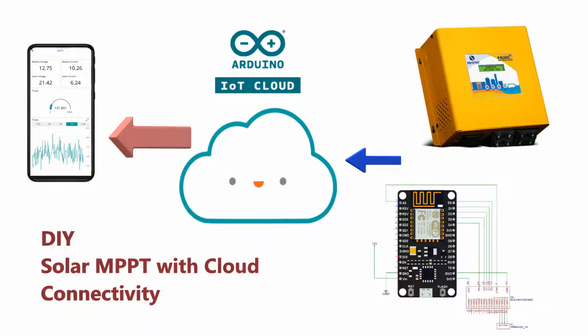With this information I started reading the values and tried to verify them on hardware. For this I used a NodeMCU. The thing is, the NodeMCU has only one ADC channel, but we need at least 4 ADC inputs: solar voltage, solar current, battery voltage and battery current.